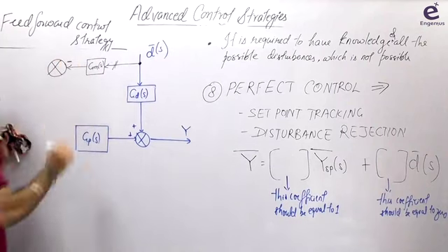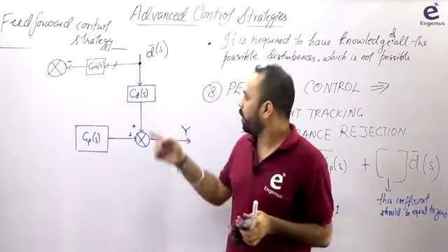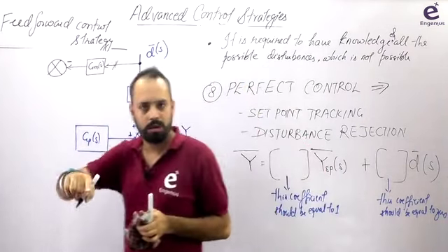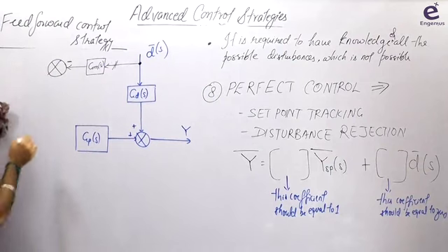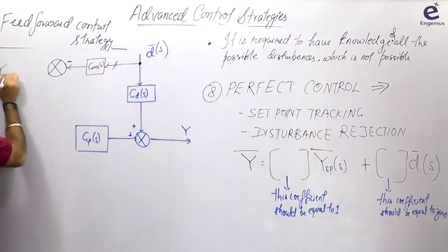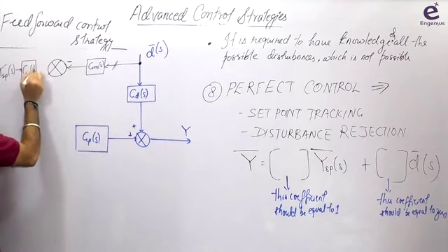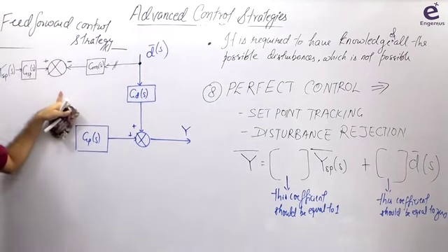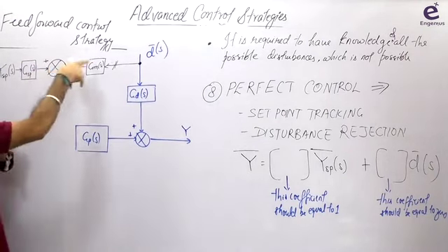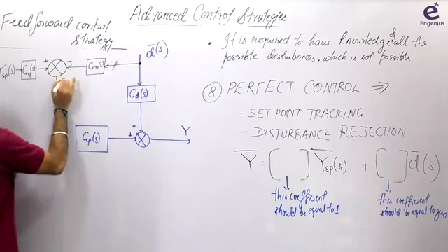So there are a lot of similarities in feedback control and feed forward control. My measurement is being compared with a set point. So this will be the set point, YSP. This set point YSP bar S goes to a block which is GSP, again GSP was there, with a positive sign. Whenever the set point and the measurement are compared, we know that there has to be some error. This is the error function.